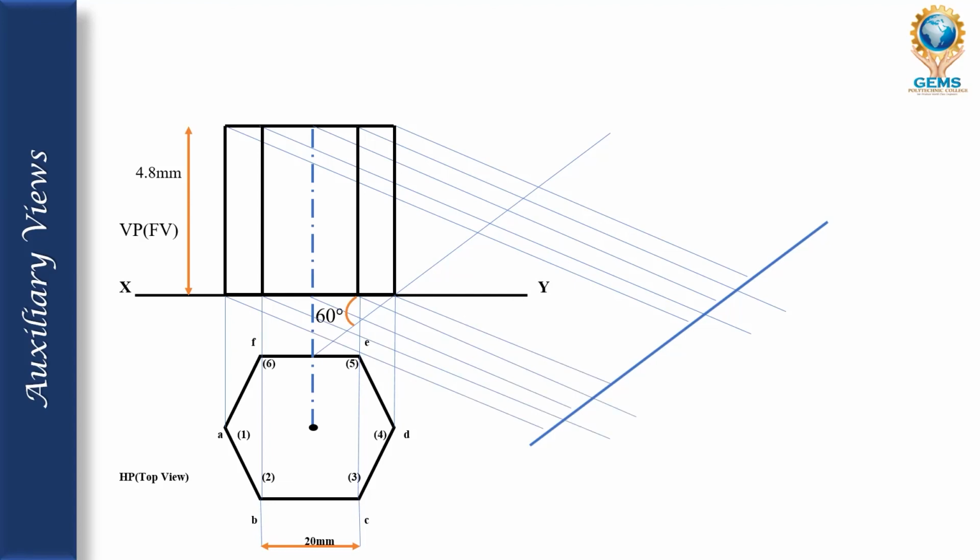So perpendicular to the 60 degree line, and the same here, perpendicular to the 60 degree. Now this line will be connected together, and we will get an object like this by using the dimensions. Keep it in your mind, you have to use the dimensions. From the center the base is 25 mm. Keep this side 25 and that side also 25, and just connect it.